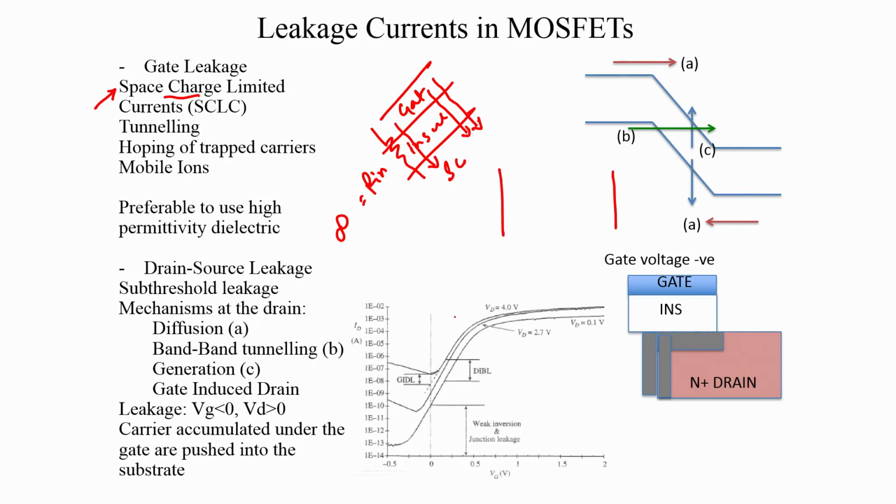So, the idea is this: you have an electric field across say two plates and you inject a lot of electrons inside. Now, what is the electric field felt by an electron here and what is the electric field felt by an electron here? If there was only one electron present in this region, we would say that the electron experiences a certain field and therefore it has got a certain drift velocity. If this is a semiconductor, it has got a certain drift velocity which is mu times the electric field, and this contributes to the current.